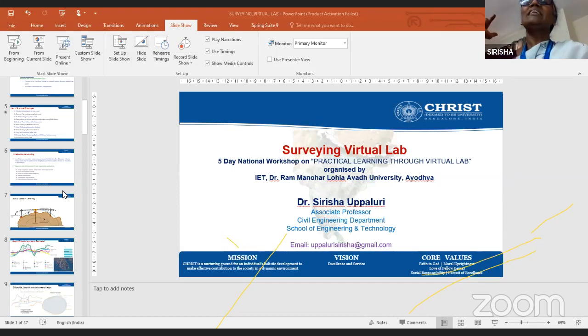Is it clarified or not? Any further doubt? Chainage means the distance from one staff position to the other staff position. Not from the instrument position, not from the telescope position. It is between two staff stations. The first staff station you can take as 0 chainage. The second staff is at 20 meters or 30 meters, depending on the chain or tape you are using: 0, 20, 40, 60 like this. We append at every 20 meters.